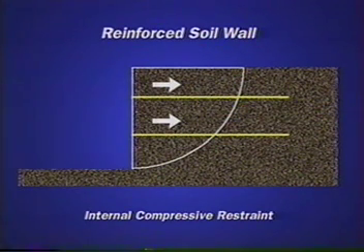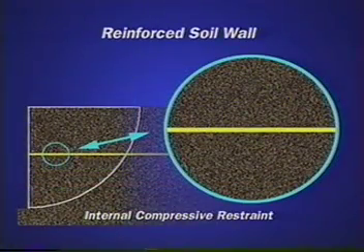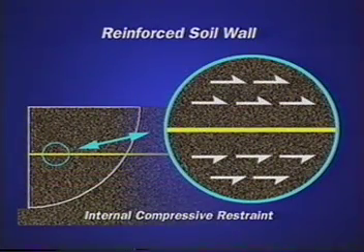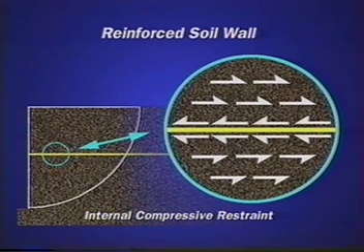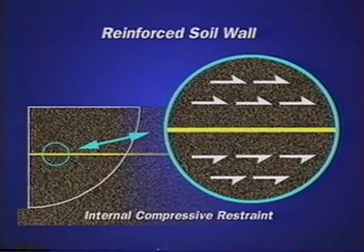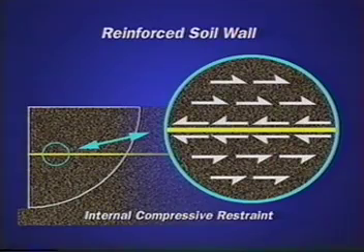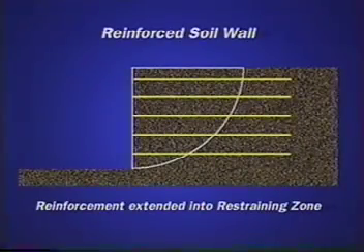After reinforcement is placed, initial tensile strains still develop within the soil. However, if the reinforcement is of low extensibility, these small strains lead to relative movement between soil and reinforcement. As these stresses are of opposite direction, they induce compressive stresses in the soil and complementary tensile loads in the soil reinforcement. The end result is a stable mass of reinforced soil comprising two zones.